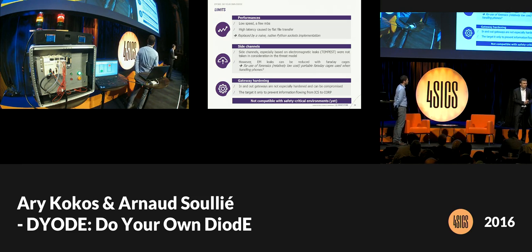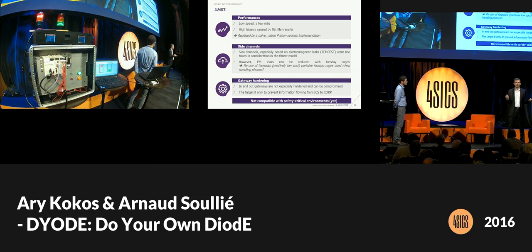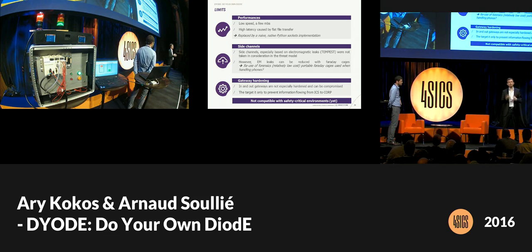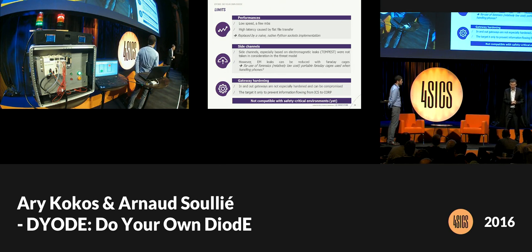Here, a very cheap solution is to buy Faraday bags. In forensics investigations, you have Faraday bags which cost between 5 and 30 euros, and since the Raspberry Pi is quite small, you can put every Raspberry Pi in a bag and just have the optical part going from one bag to the other. Like this, you can limit the emission.